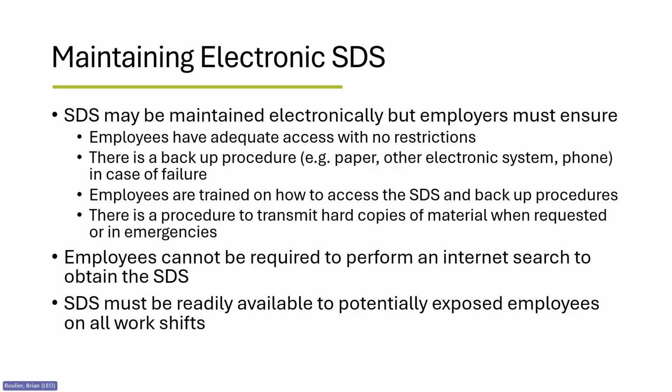Safety data sheets may be maintained electronically provided the following conditions are met. First, like hard copy safety data sheets, employees must have adequate access without barriers. Barriers may include computer terminals that are not always accessible, requirement of a password that's not readily provided, or other restrictions which limit employee access.